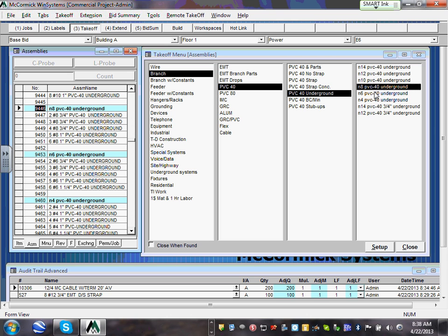Okay, so here's all my conduits for the parking lot. And how many conductors? Now, I have 48. Here's my advice for all of you: use multi-wire branch circuits, 3 phases and a neutral. So if you went outdoor and you have, I don't know, 2 circuits, then you can grab, in this case, 3 conductors.